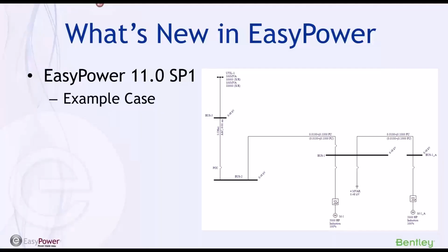and then construct your system with a load which includes the second harmonic order current injection, run it, and see what the IEEE 519 report looks like. In 10.6 and the prior versions, the IEEE 519 report was based on IEEE 519 2014. Starting from EasyPower 11.0 Service Pack 1, the IEEE 519 standard limits are converted to the 2022 standard. If some customers would still like to go with the 519 2014, we will show you how to construct a report by yourself, so you can customize it.